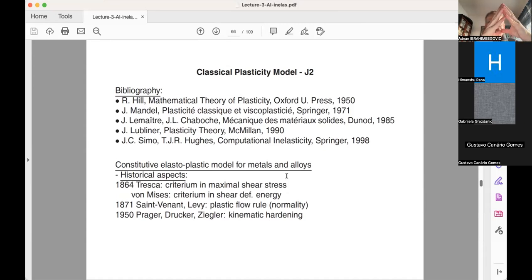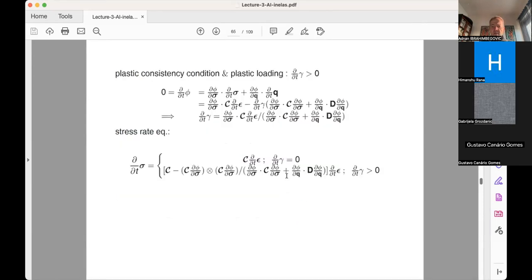So basically, since you have a change of shape expressed with the deviatoric type of stress, it becomes very simple to handle. You only have one type of mechanism, and if you take this tensor notation, you go back to features that you already recognize from the 1D case. So it's not only in terms of formulation, but also in terms of computation, you recognize many steps and they become basically identical. The only difference is that the elastoplastic tangent modulus in the continuum case and the discrete case, contrary to the 1D version, is no longer the same.